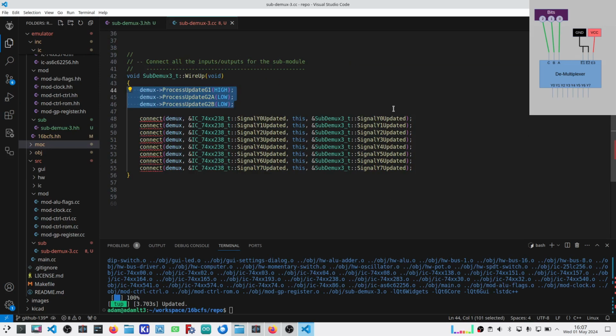The outputs are always going to be enabled, and that is because I always want to be outputting the control signals. So no matter what the size of the demultiplexed word is, I always want something to be outputting. Therefore, whatever is appropriate to be enabled will always be enabled. It gets a little bit more complicated with 4 and 7 bits.